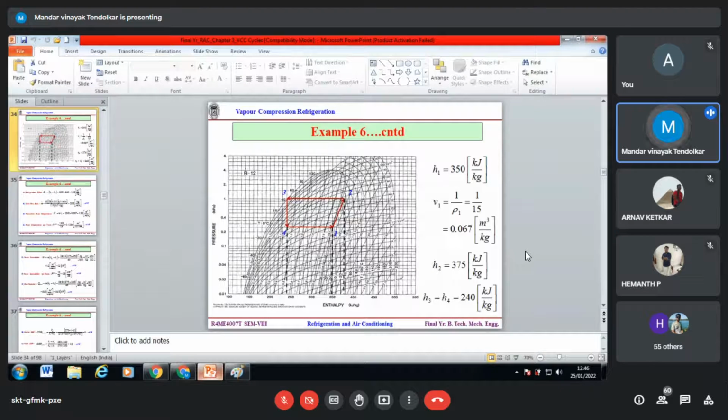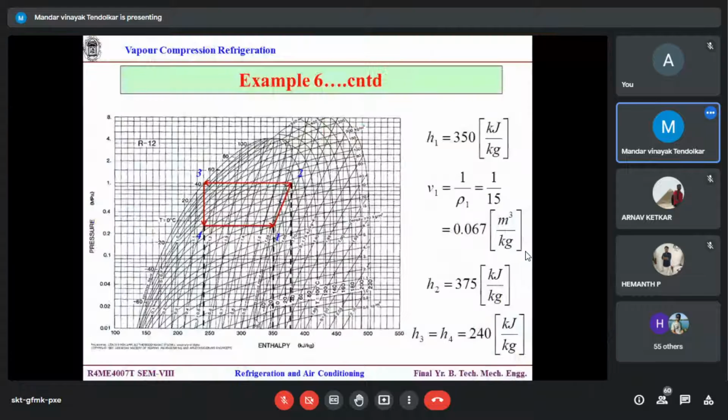Now coming to our part. So this is my HG, vapor part, correct, over here. Then it is falling between these 2 isotherms, isentropic, sorry, not isotherms. Isentropic lines, correct? So find out the distance at this particular pressure between the two, find out the ratio here, and join.